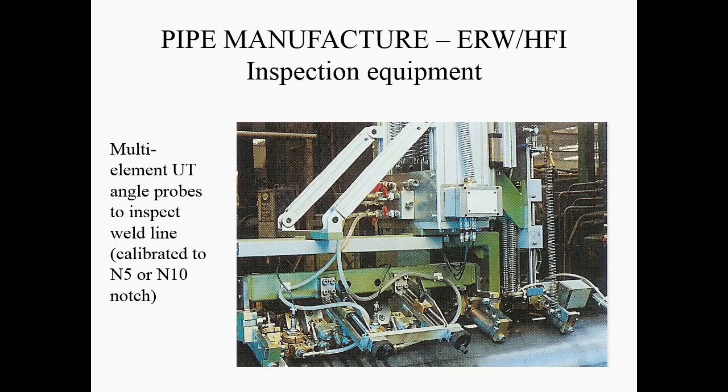And the microstructure of the material will not change? Will not change. If we can keep the temperature below about 700 degrees C, the microstructure doesn't change in the time that we've got this process to run, because it's running in a few minutes. If you held the material at 700 degrees C or 600 degrees C for many hours, then it would change. The perlite would become spheroidized. But we never do that.